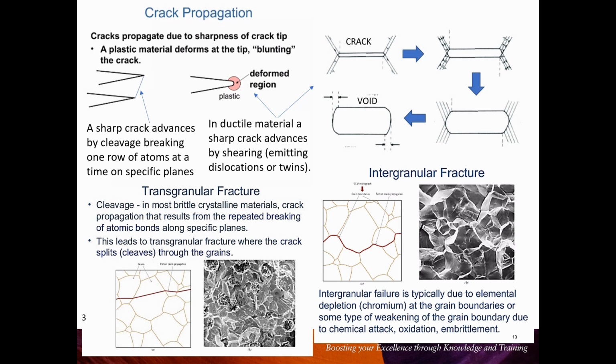But we do deal with ductile materials, the ones that you'll commonly know in reactor operation, which are austenitic stainless steels and nickel alloys. And very important, obviously, zirconium alloys. They're used for the fuel cladding, and certainly in the CANDU reactors, in heavy water reactors that run on natural uranium, much of the core internals are made from zirconium alloys.